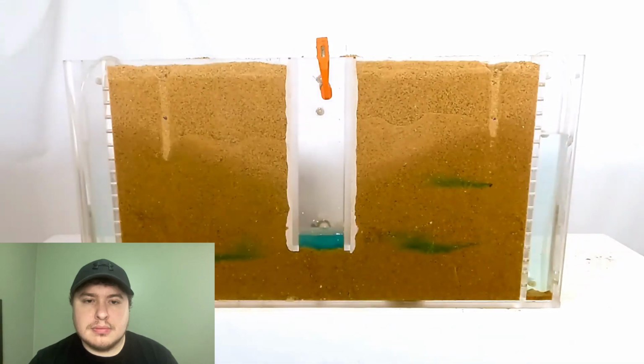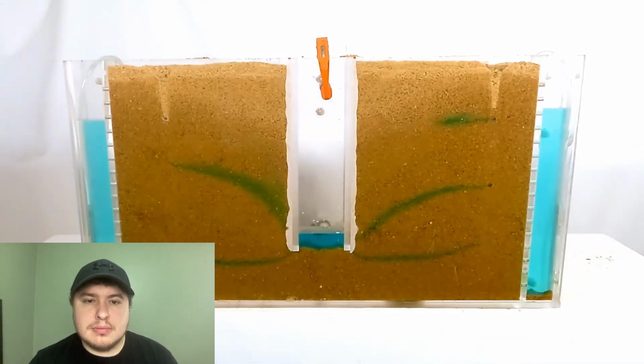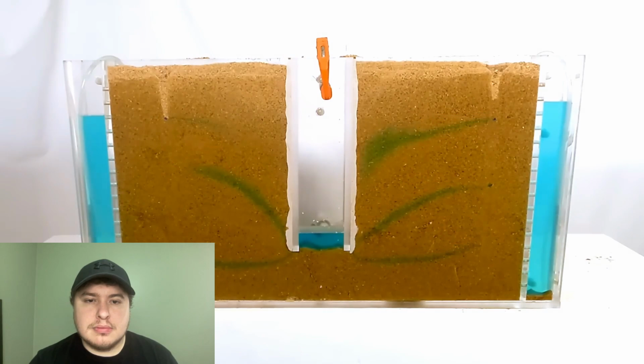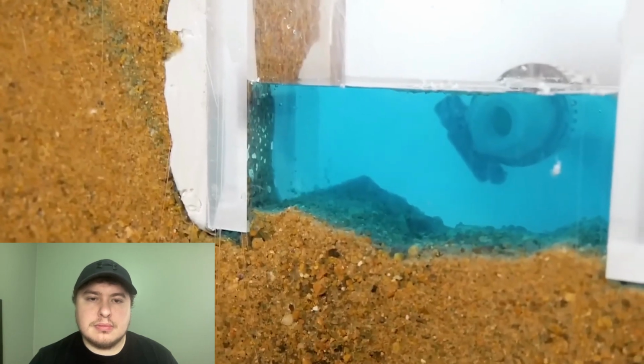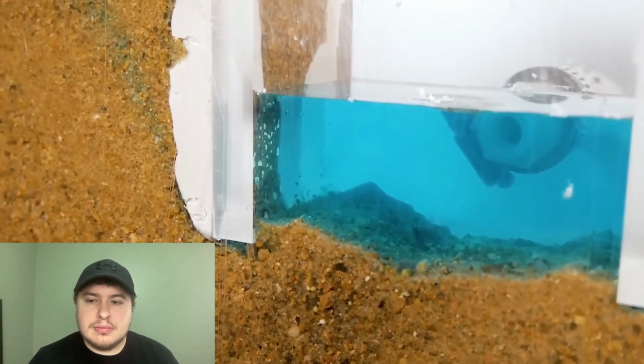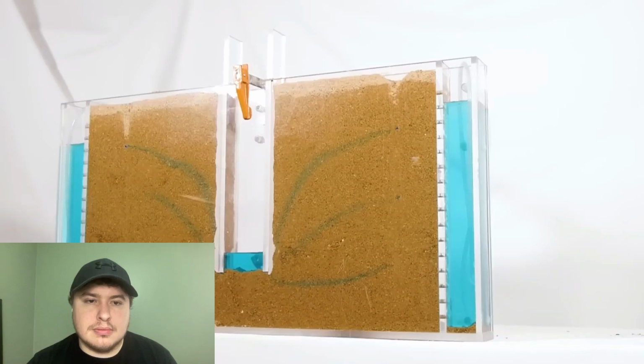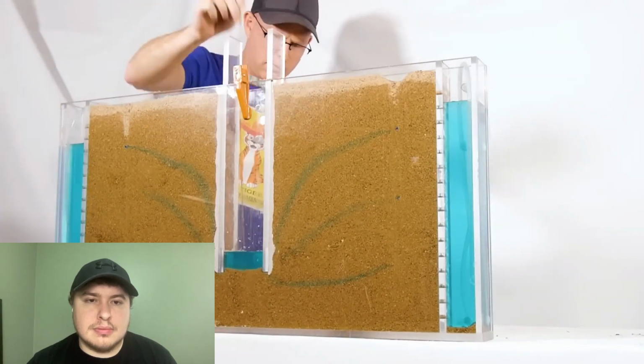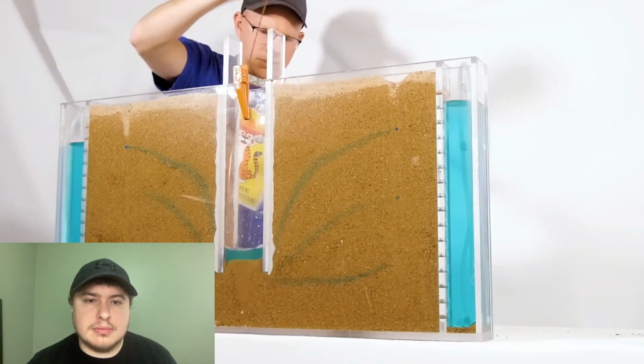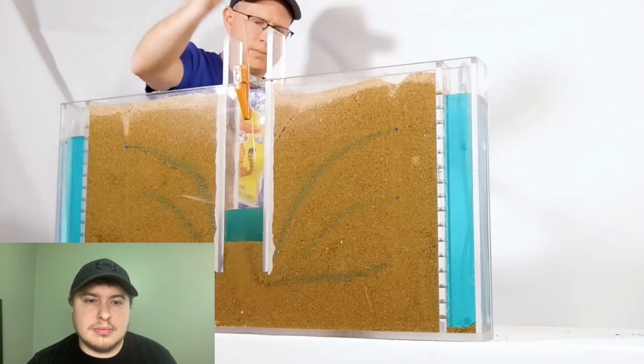And as you know, distance matters when it comes to groundwater because the shorter the flow paths, the greater the hydraulic gradient, and thus the higher the volume and velocity of seepage. If you look closely, you can see the sand boiling up as the seepage exits the soil into the bottom of the caisson. This elevated pressure in the subsurface and high velocity of flow means that the soil particles themselves aren't being strongly held together.